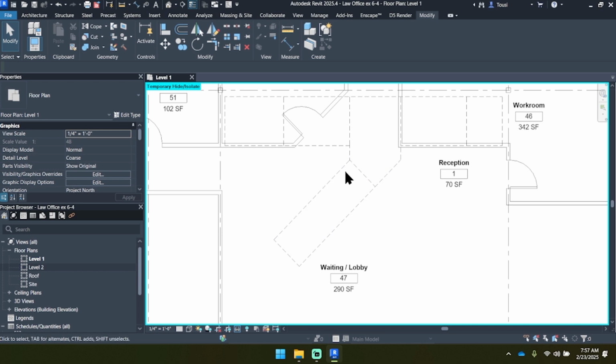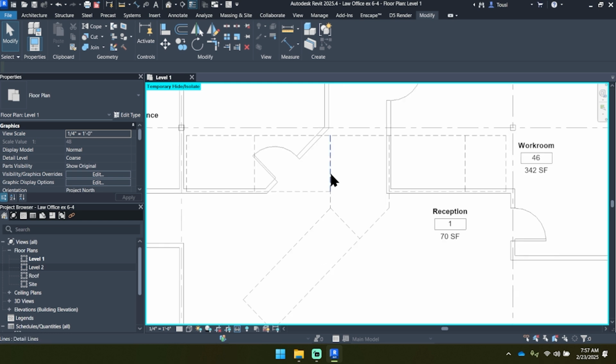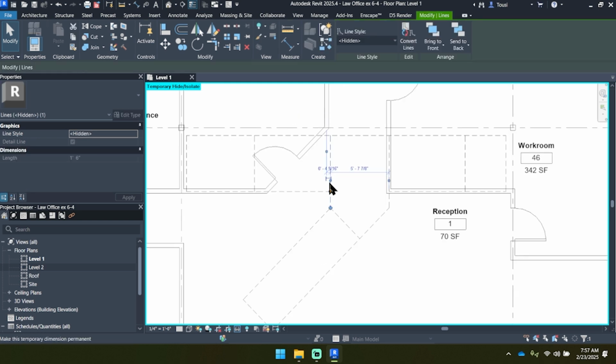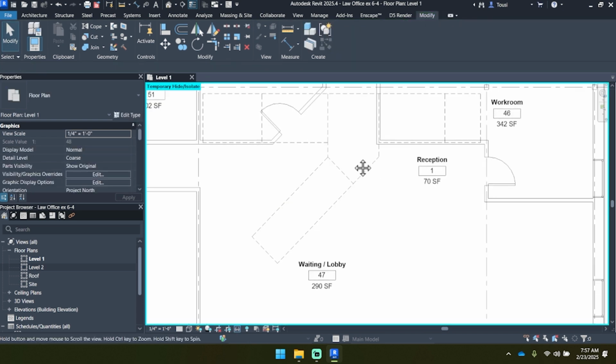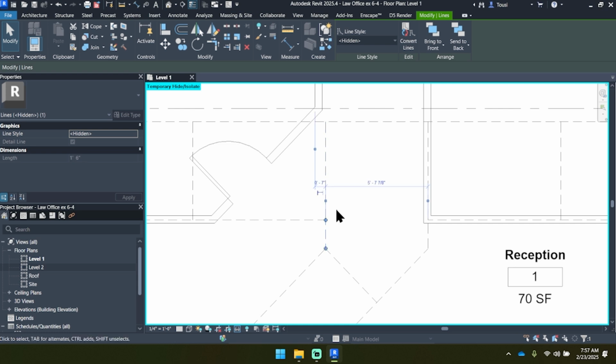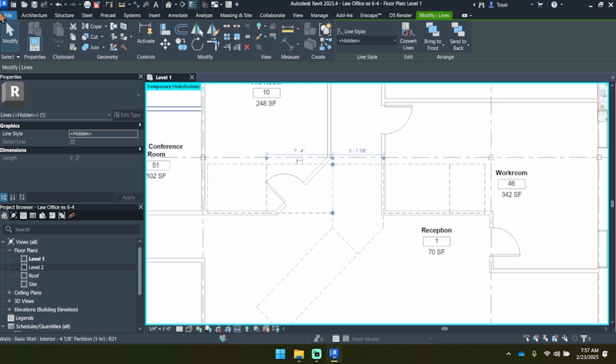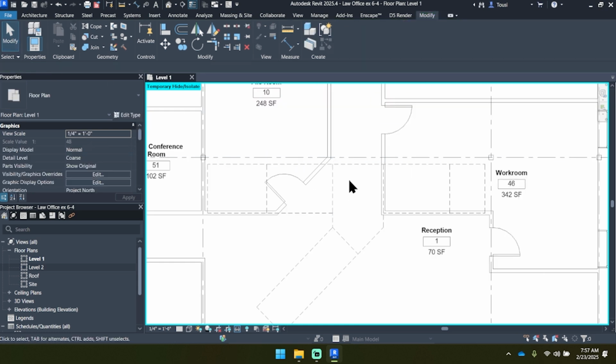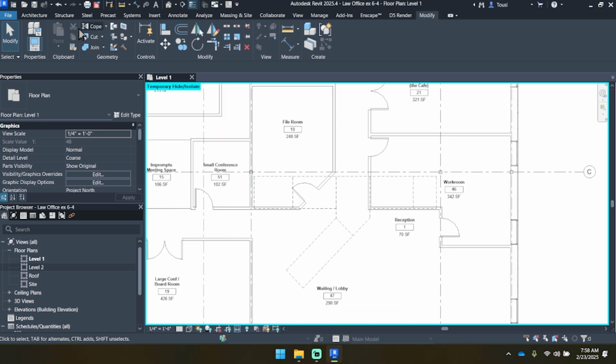Once you have this line work in, and it fits the dimensions as required on page 8-40, we can get our stairs going. It is going to be important that these 2 lines are 2 separate pieces of line work. So if you were being efficient, which is great, but not necessarily in this case, please ensure that these 2 lines are 2 separate line works. Otherwise you will have trouble drawing your stairs today. So let's get that stair tool going.